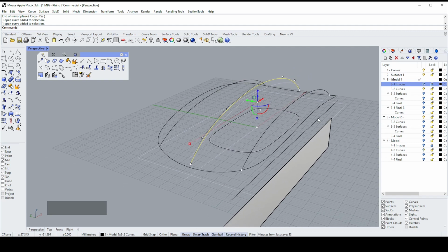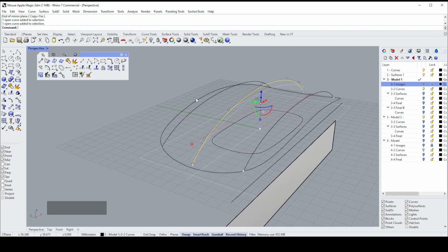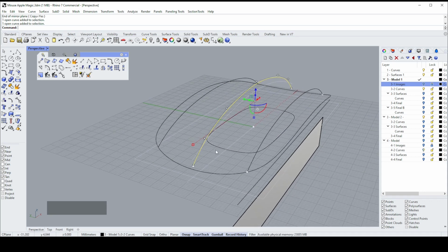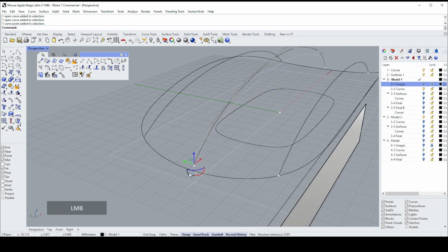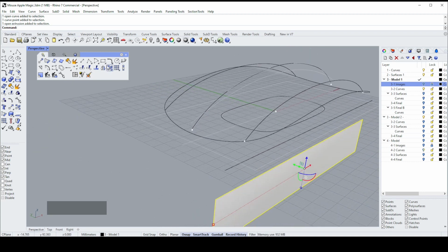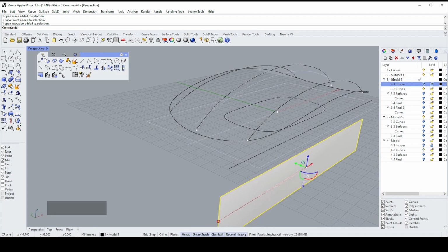I don't need to do that because in fact you can still create a compound surface with the lines not touching, but it won't create as smooth a surface. So I want to get that point onto the middle of this point. So I'm going to move this plane, which is becoming very useful. I want to move it to the 0 point.